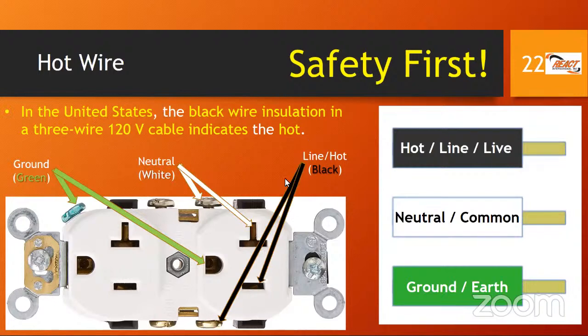We're also showing a couple of arrows here to show what it's connected to on the outside, the slot it's connected to when you plug it in. Even though you're connecting the wire to this screw on the inside, this screw is actually connected to this slot, the smaller of the two slots. That's the hot. And the white is connected to these screws here, and it also ends up connected to this slot on the outside, the larger of the two slots.